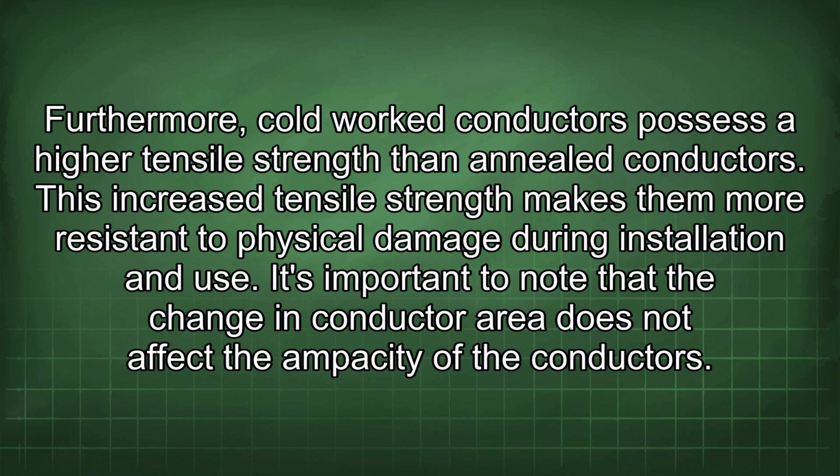Furthermore, cold-worked conductors possess a higher tensile strength than annealed conductors. This increased tensile strength makes them more resistant to physical damage during installation and use. It's important to note that the change in conductor area does not affect the ampacity of the conductors.